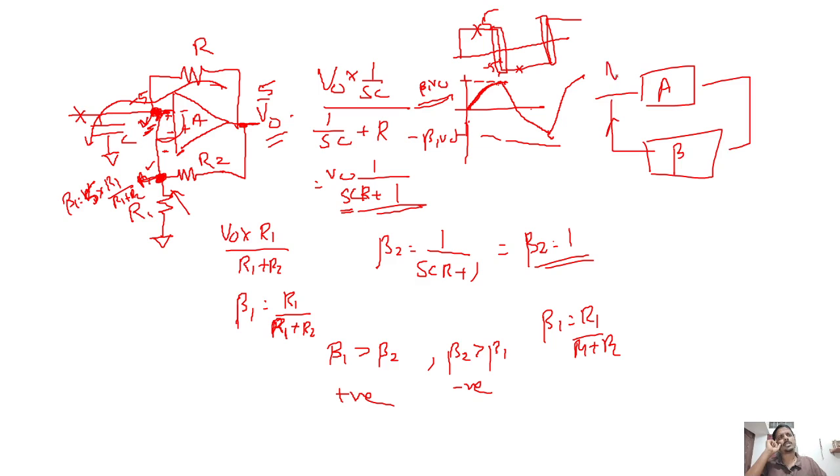Like if I have a signal like this, if there is some phase difference, definitely the voltage difference is being amplified, so again the voltage will decrement slowly. Instead I want a summing up, so I just want to make both these in phase, then only it will be added up. So that's why we require a positive feedback circuit.